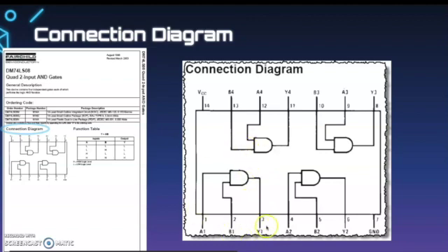So that's how those function. We also have pin 7 as ground and pin 14 as the VCC, or our connection to power. Each of these components has to be connected to power individually.